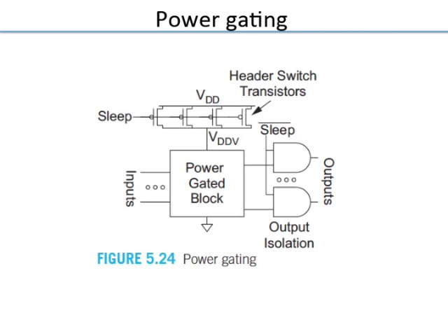It's like a triangle, right? So the total current will be the sum of all these little triangles. Now if every gate switches, then you will have a lot of triangles adding up and the instantaneous current can be very large. But not all gates switch. Activity factor, as we said, is small. So that becomes a tricky thing.